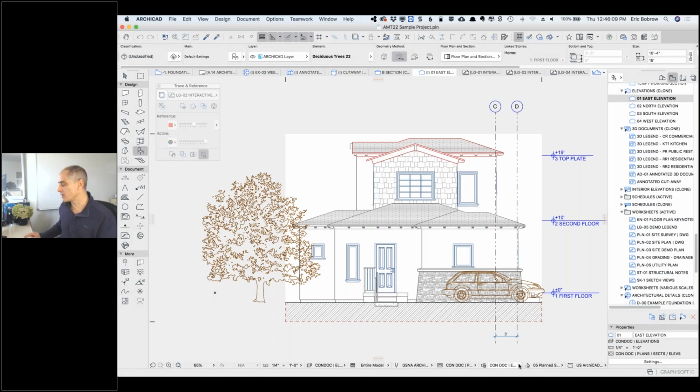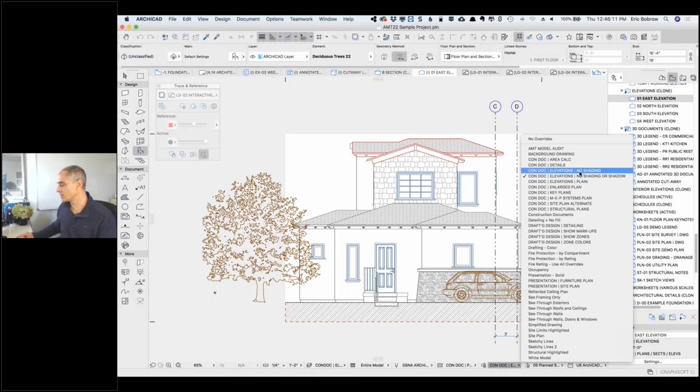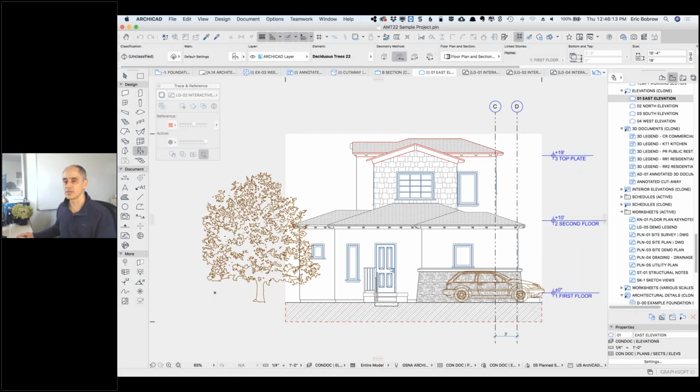And I can also go and say I'd like to have it just plain, and then the vector line work will disappear. So these are using graphic overrides that are built into MasterTemplate. Again, built into ArchiCAD, but just very, very conveniently there. You don't have to have multiple different markers to create a rendered view versus a plan view. So I wanted to show you that.